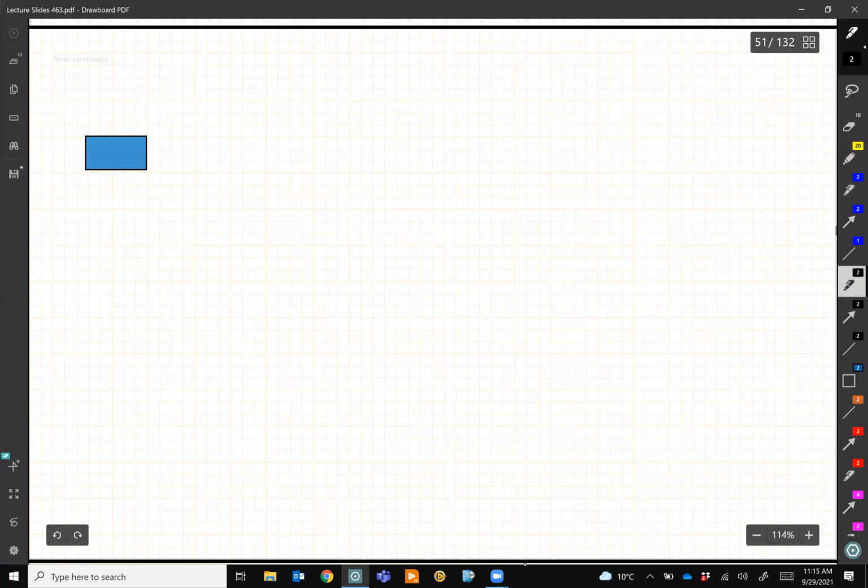base motion. All right. What is base motion? We said, let's say you have a mass m, and let's say this is suspended from a spring K. And this time, you are moving this point up and down. We call this point the base. I know the example that I showed you was upside down, but it doesn't matter. Intentionally, I drew it like that.